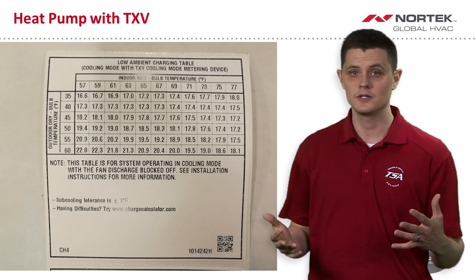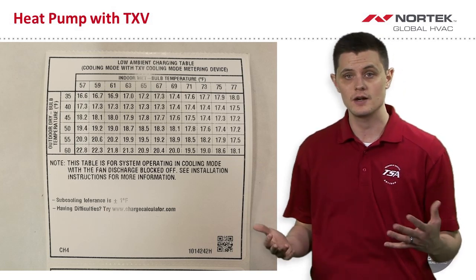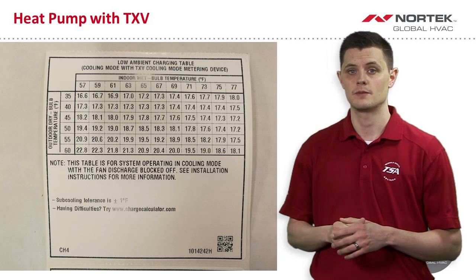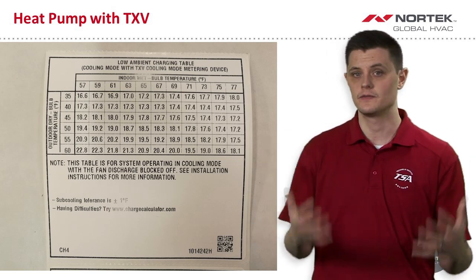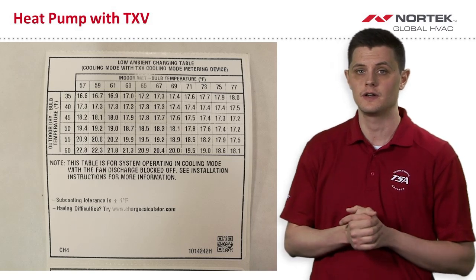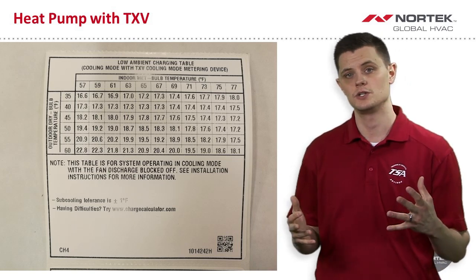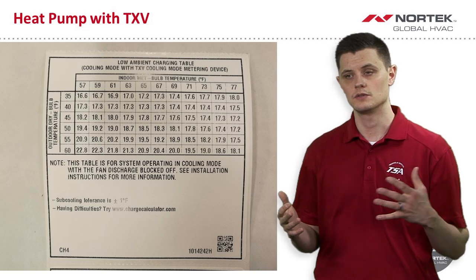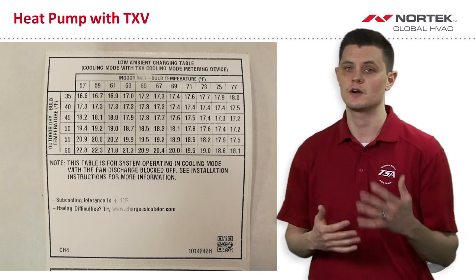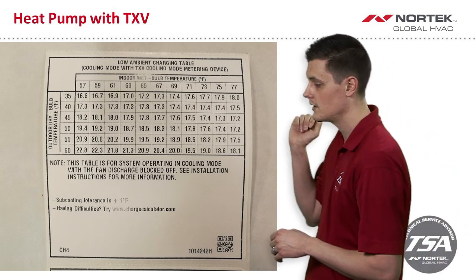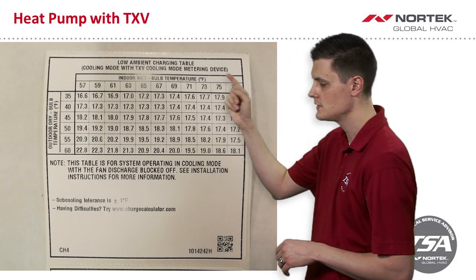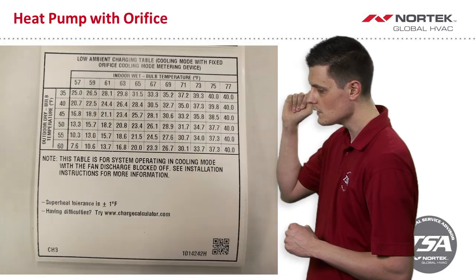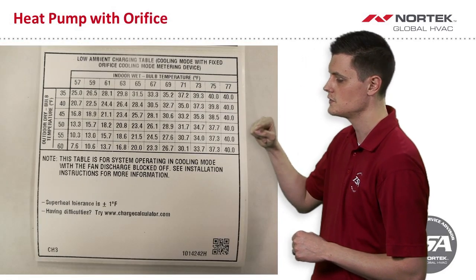Most HVAC manufacturers require an indoor wet bulb for proper charging. So again, that's just a vital tool that the techs need to have in their arsenal when they're going to troubleshoot an HVAC system, especially our equipment, where we're really requiring an indoor wet bulb, because based on what that wet bulb temperature is, it will determine what the superheat number is.